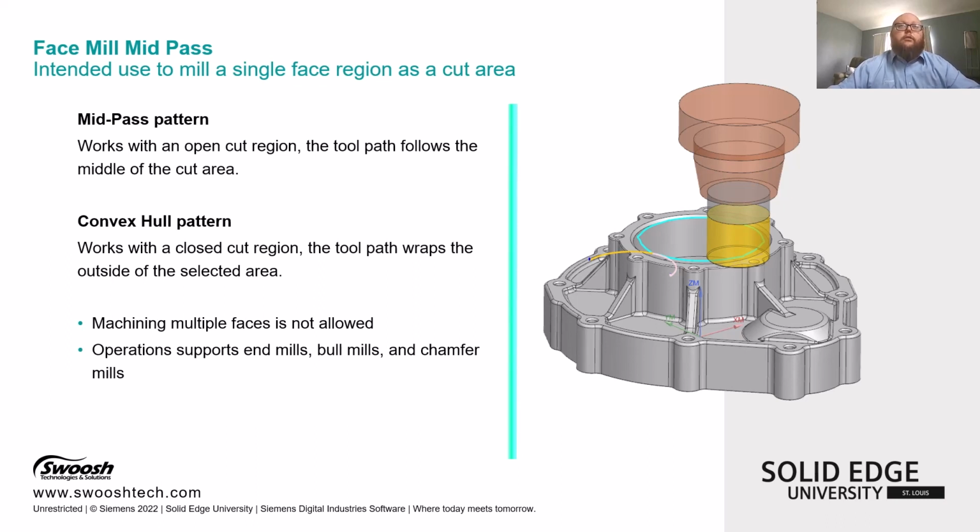For any time you're looking to face mill one piece of geometry, like in this case, this is a great example: we have a face with a bolt pattern on it. With a typical floor wall or floor without wall operation, you would likely have to play around with a number of settings to get a nice reliable toolpath that you would like to see. But now with this operation, it's intended for these kind of single-pass face milling operations.